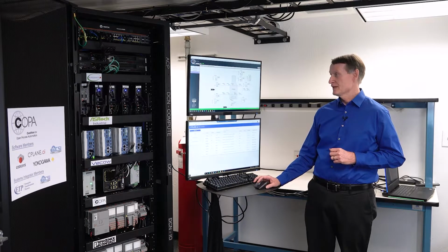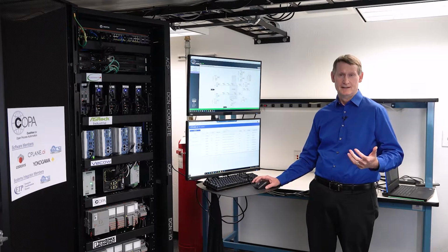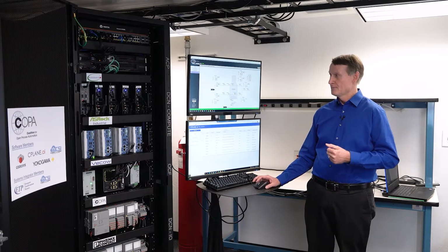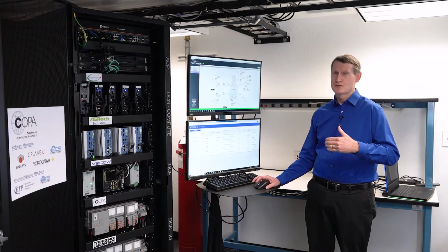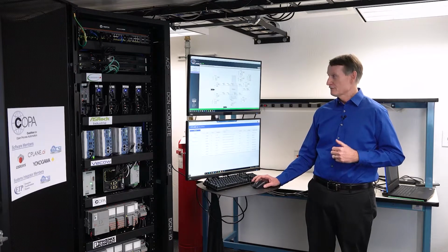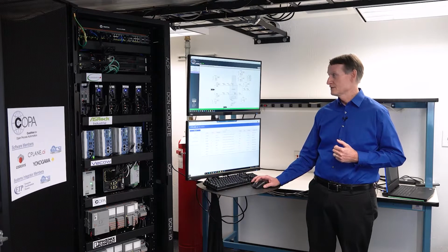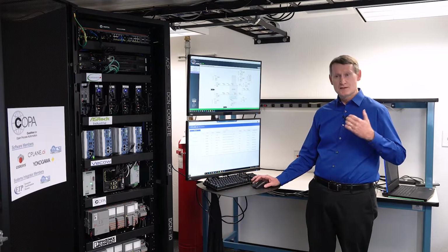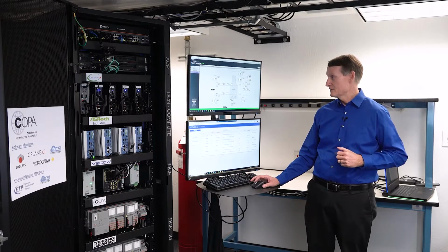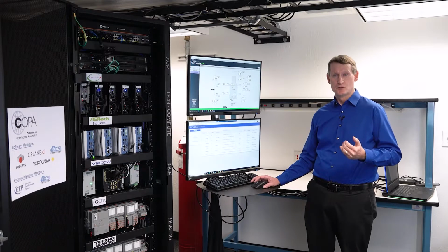Secondly, we'd like to send as much flow into the heater as we can. We'd like to maximize the flow rate because this is at the front of the refinery, and the profit of the refinery is directly proportional to this flow rate. And then third, for safety reasons, we want to make sure that we don't burn up these tube skins. So that's essentially the problem. We want to maximize flow rate. We want to keep this temperature. But most importantly, we want to make sure we don't burn up the tubes.